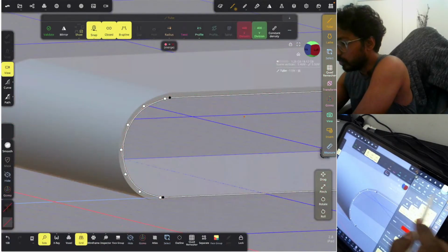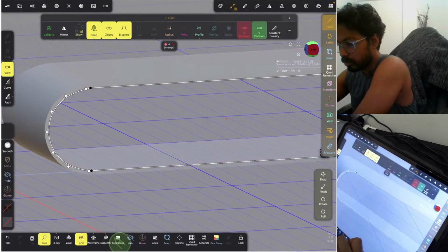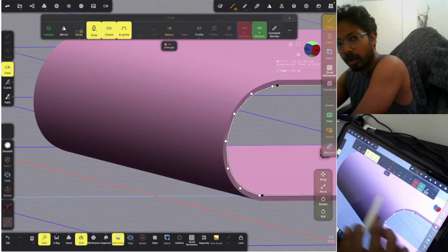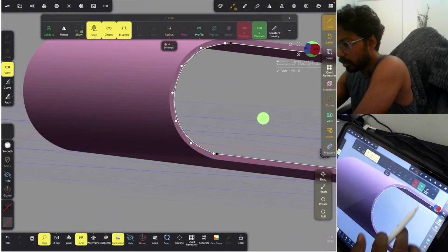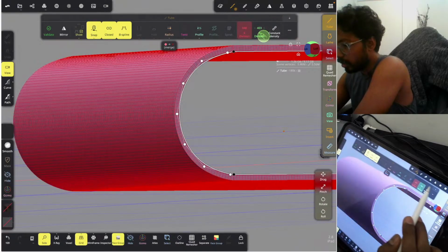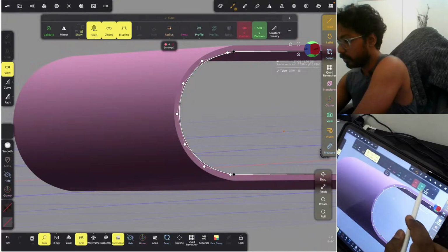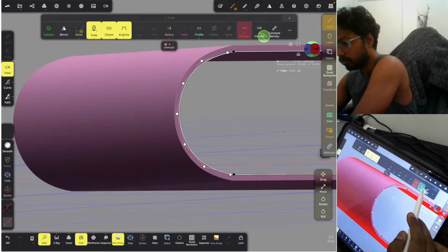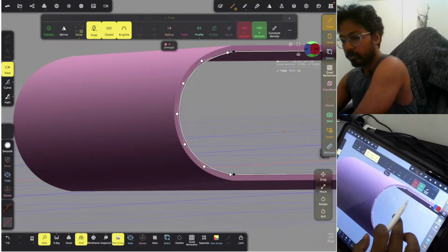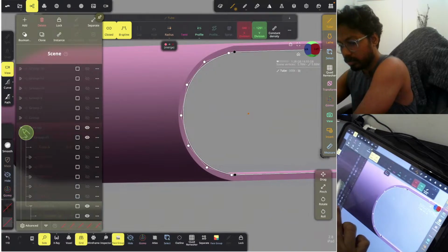And if you remove the smooth shading and look in the face group view, yeah, the layer lines are going to be visible here, but when you actually print it, they don't show. If you are worried about the smoothness of your 3D print, you can go further until you don't see any seam lines in this view. It is so smooth, but the challenge is the file size is going to increase.